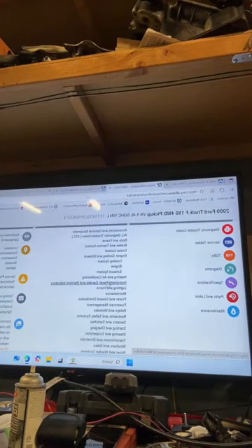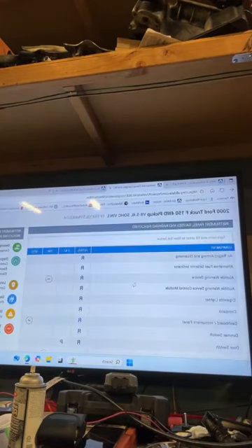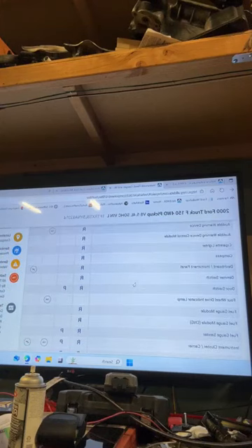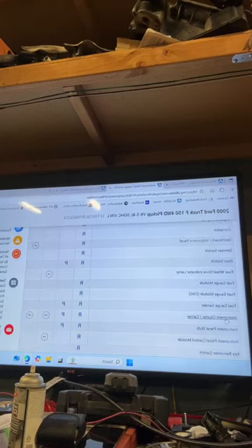There we go. Instrument panel, gauges, warning indicators. It's because if that circuit isn't in there because your truck didn't have a tach, you're going to be stringing wire through the engine bay, through the firewall, up into the cab, and then through the dash to the back of the instrument cluster.